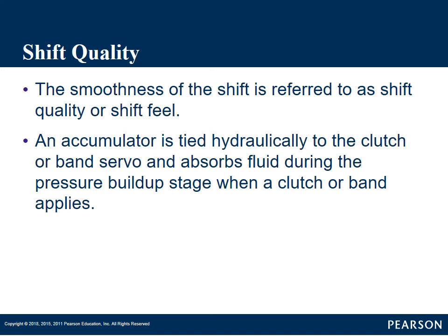All these can lead to, say, a long drawn out shift can lead to a slipping or sliding condition, which is hard on the clutches. A real short shift or harsh shift, the customer is really going to feel. So shift quality in a transmission is extremely important. Your manufacturers go through a lot of trouble to make sure that that transmission shifts in a way to where customers won't complain, but still has longevity and life to that transmission.